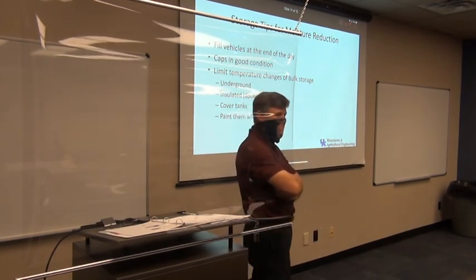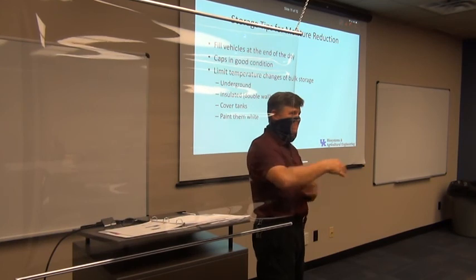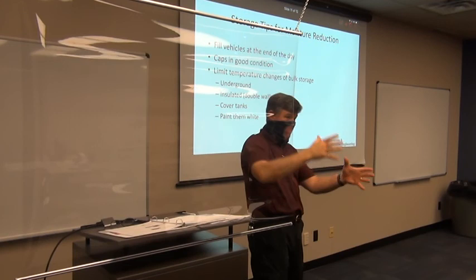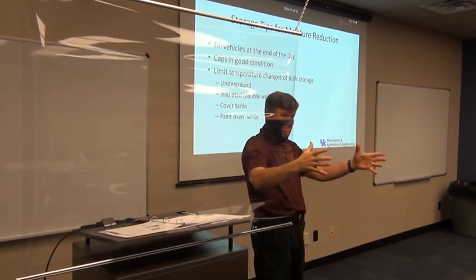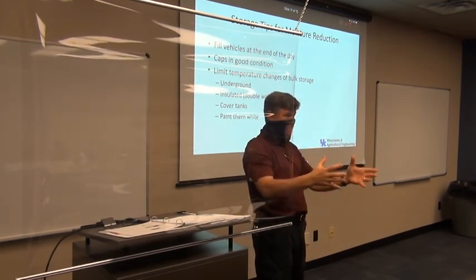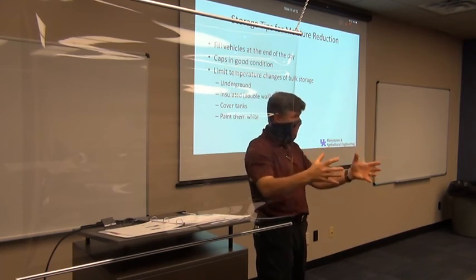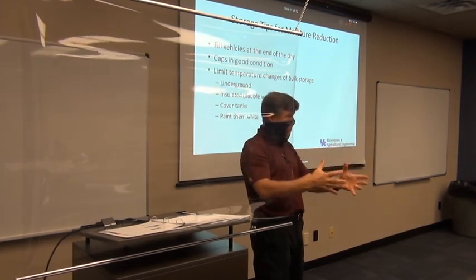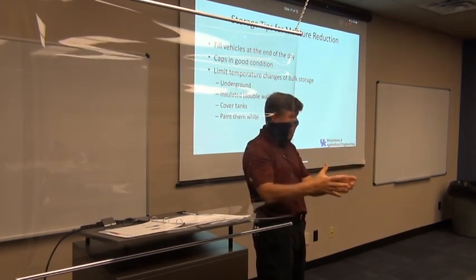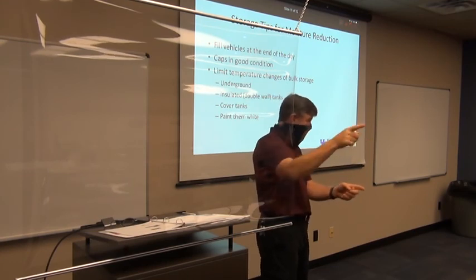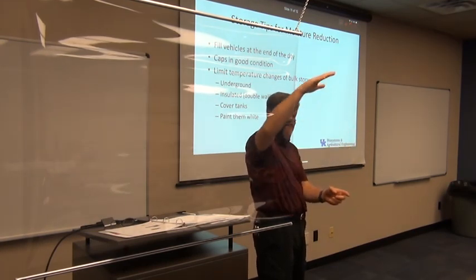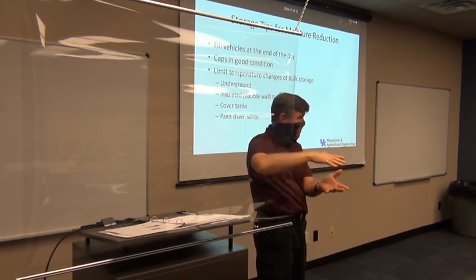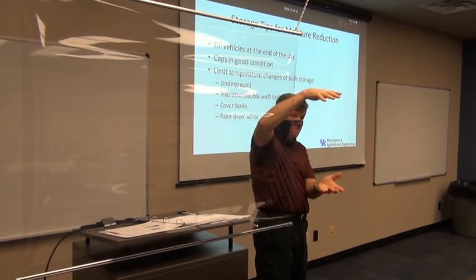Right? What happens when air cools? Water in the air is going to condense. The air is going to cool, so it's going to be a couple things. Think about the air in the tank as it cools off. What's it going to have a tendency to do when stuff cools? When it gets hot, it expands. When it cools, it's going to shrink. It's going to get smaller, which is going to pull air in, and then we're going to get that condensation, because at nighttime the relative humidity goes up and the temperature drops, and we get up close to that dew point.